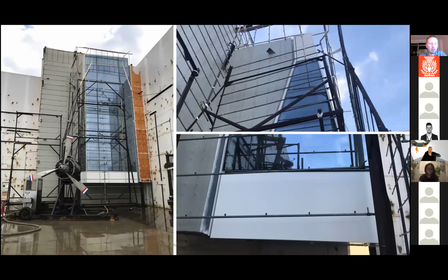It's a couple of different companies across the world and in the US that do this full time. These are testing labs basically, and they have various decommissioned plane engines that are blowing water at a certain predetermined speed. So you simulate very strong wind-driven rain from the side onto a full-scale portion of your building that has ideally been built by the same people that are actually going to build the building eventually.